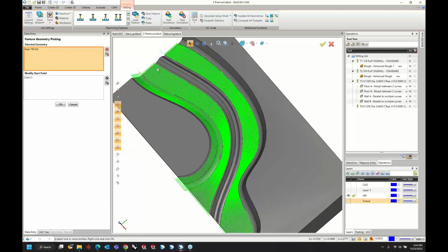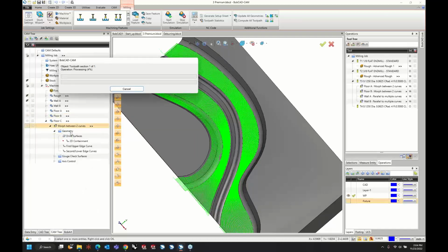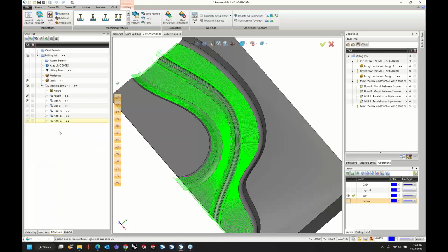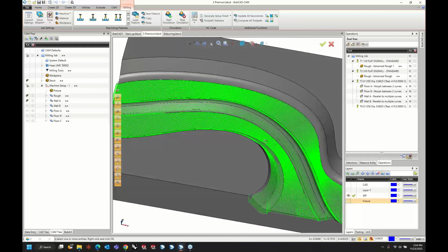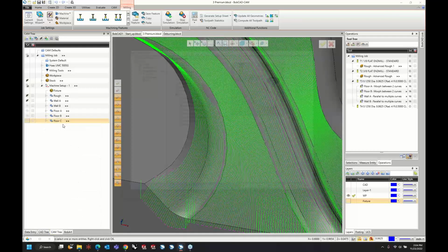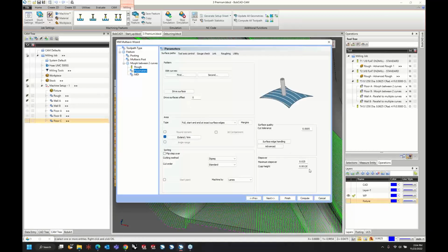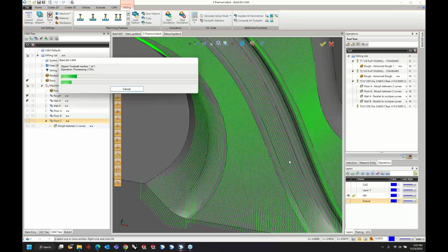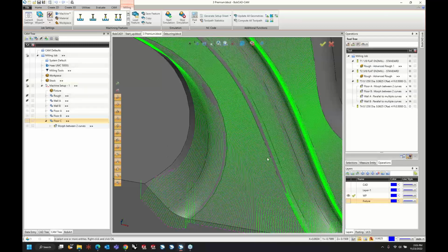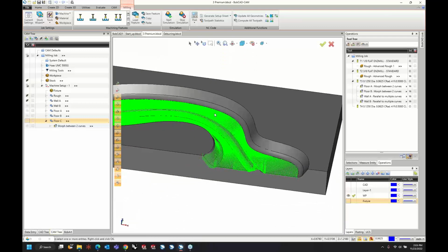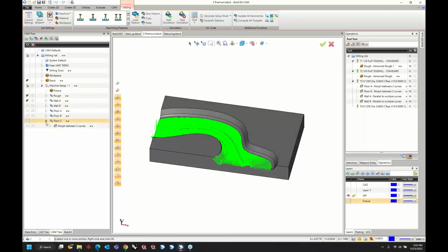And then my first upper edge. And again, it doesn't matter which one you're picking, as long as you're picking opposite edges. A lot of these, when you're using them for 3-axis, you can kind of copy and paste the toolpaths and they'll work out. Like this one, I might need to tighten up a little bit. Maybe go to like 10 thou, just so I get a little better result on the top there. But the multi-axis are really great for this, those premium toolpaths.